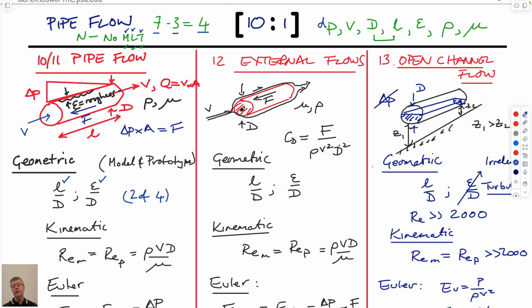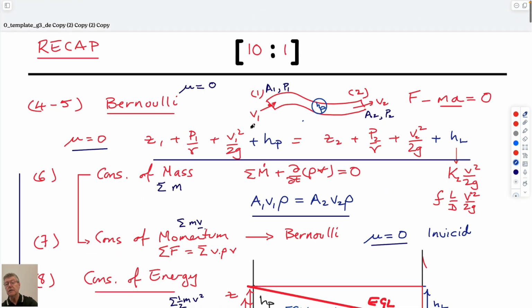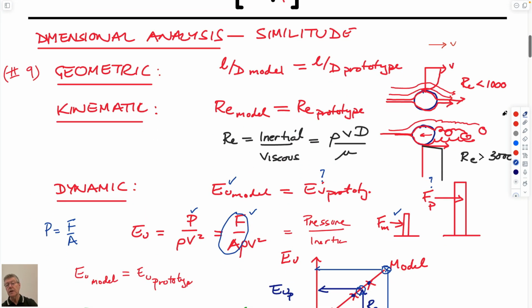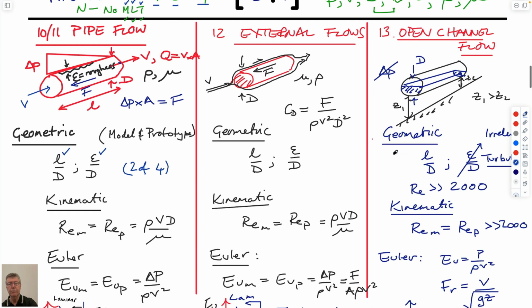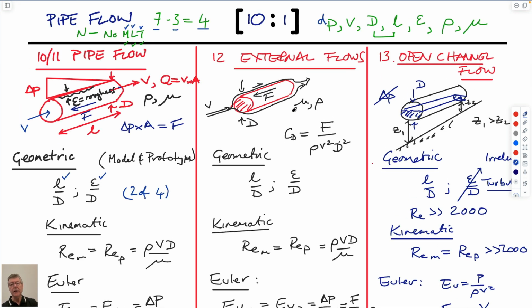Well, you could think of a closed cylinder as also kind of the same as an open tube. So flow past the closed cylinder is that the flow hits the stagnation point at this end, goes around it, and comes out the other side. For this geometry, you'd expect the behavior that we talked about. At low flow rates, it would be creeping flow. It would hug along the side of the container and over the back side of it. And at higher velocities, it would have vortices off the back side of it.